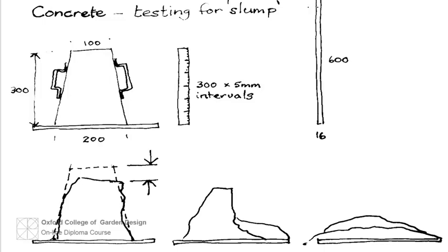These voids to be removed are not the same as those produced by an air-entraining admix to produce minute air bubbles. These microscopic bubbles give improved workability and resistance to frost damage by acting as safety valves for expansion of the ice crystals. Secondly, durability depends on proper curing, which is described in a minute.